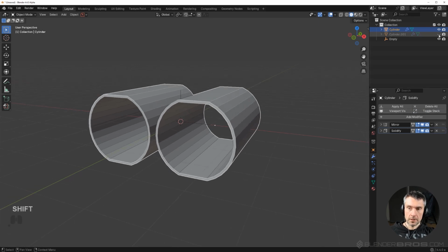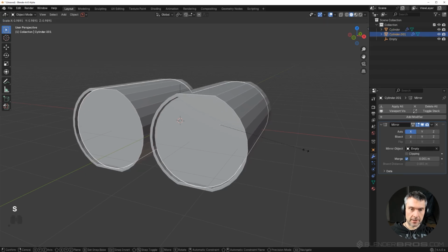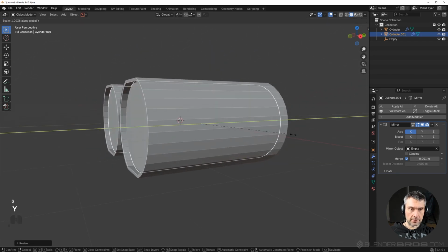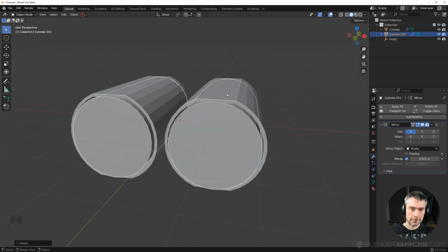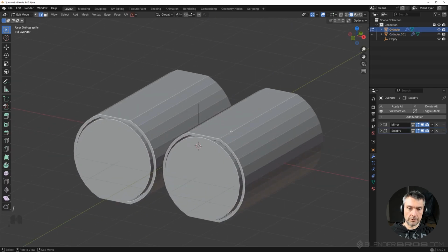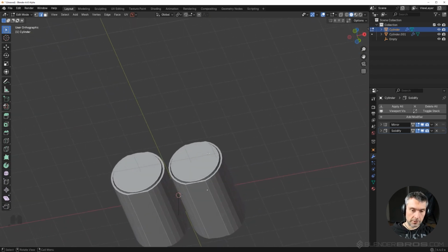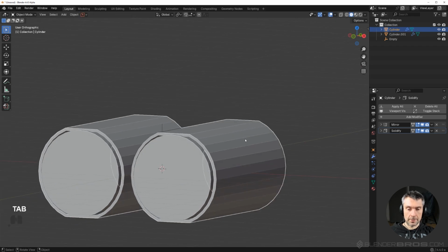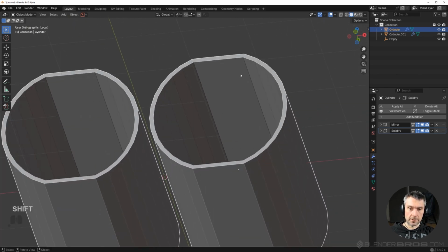With this done, let's turn our cylinder back on, and we're going to make it a bit smaller. So select the cylinder and just scale it a little bit. And we're going to make it a bit longer, just so it sticks out a little bit outside of this frame, okay? So now, what we can do is cut this top either with a Boolean, or we could simply use the existing topology. So let's grab this element here, and press / on the keyboard to go to local view, because we want to see what's happening underneath, right?